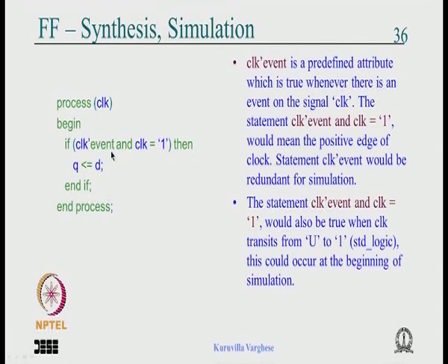But for the simulator you know that whenever there is an event on the clock it starts computing. When it comes here there is a repeat, there is something redundant. The process starts whenever there is an event, and this is again a clock tick event. So this is a redundant statement as far as the simulator is concerned, but it doesn't matter, it's a repetition but it doesn't harm. So this is the code for a flip flop which works as an edge triggered flip flop for both the simulator and the synthesis tool.